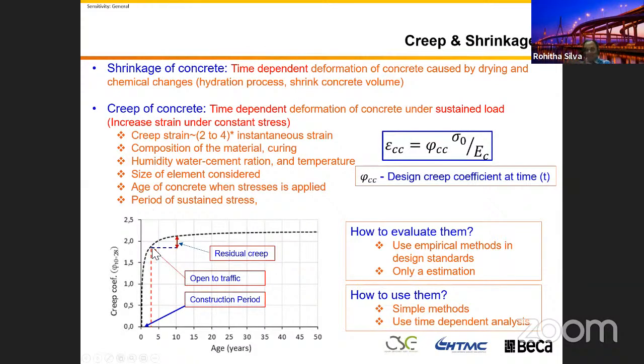Sometimes you need to pay attention. Sometimes you have a step in your design. You have to change your expansion joint from the strip seal joint to a finger plate joint. You will learn this next week. That makes a significant difference in your bridge expansion joint design, performance, and the cost. As an engineer, we need to look at this in a logical way. That's why I put this figure and show it in here.